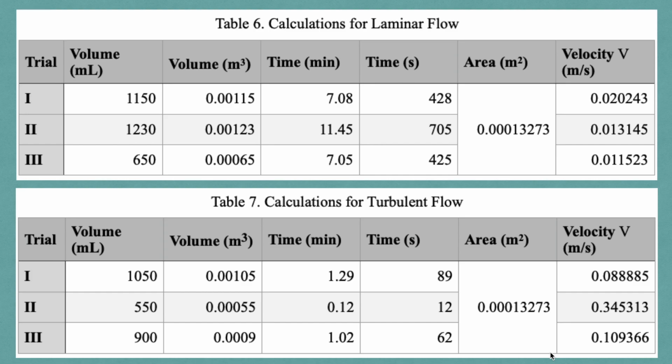These are the data that can be obtained from the experiment, as well as data that are derived from the equipment used. One of the objectives of this experiment is to obtain the velocity of the flow. The continuity equation is applicable for this experiment, as the amount of water that flows into the pipe is equal to the amount of water exiting the pipe. Thus, applying the continuity equation, we can find the velocity of the flow by the equation volume divided by area times time. It is important to note the unit conversions.